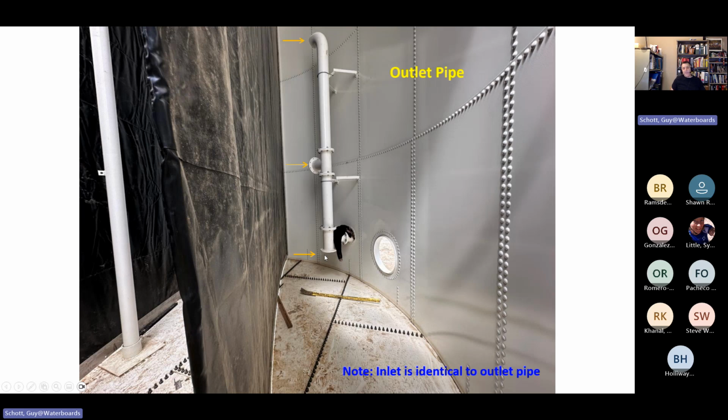What I was thinking is, let's say we do the tracer study and it's a very poor baffling factor. You can't go in, and I think this is threaded, you can't plug this off and that off, so that the water has to be forced to go out the top. Okay. And then you do another study just to verify what that is.